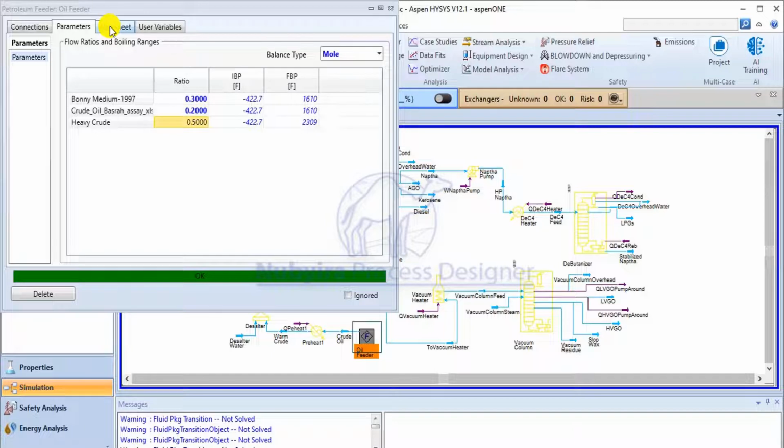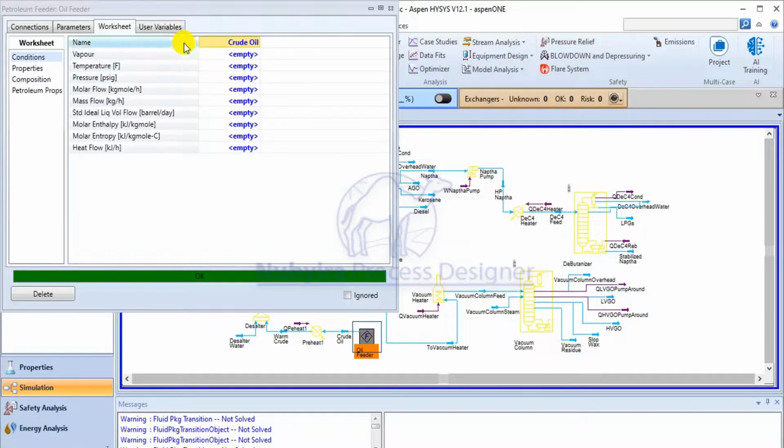In Fahrenheit, so the worksheet, you can see from the worksheet. So this is the crude oil stream that is coming out. I will flash this stream based on the thermodynamic condition. So the temperature of the crude is 100 Fahrenheit, so I'm going to write 100 Fahrenheit. The pressure is 300 psig. I think it's pounds per square inch. I don't know the meaning of the G.